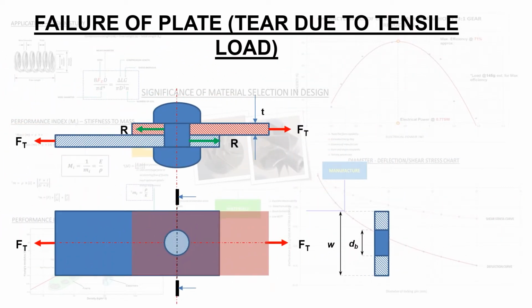Let's look at a situation whereby you have a lateral tear. We looked at the first instance, longitudinal tearing, to calculate the ideal measure of the lap to prevent the fastener from tearing longitudinally into the component. But let's look at a situation whereby the material variance around the fastener is minimum. This is where we need to calculate the ideal cross-sectional span that the component needs to have to resist tearing due to the applied shear force on the component.